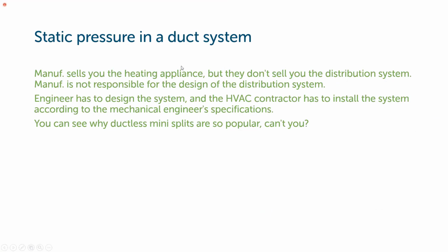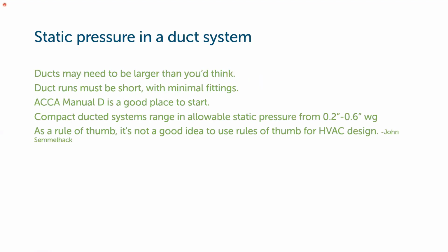So again, this is referencing what I was speaking about before, where you buy a piece of equipment that's designed to create a certain amount of heat or cooling at a certain amount of flow. And so the actual design of the system to provide that happens in the field. It does take careful design, and you've seen a lot of ductless mini splits installed because it doesn't take that level of design to put in a mini split, but you don't get the right performance necessarily with a mini split for low load rooms, as we mentioned. So this is just reinforcing some of what I spoke about a few minutes ago.